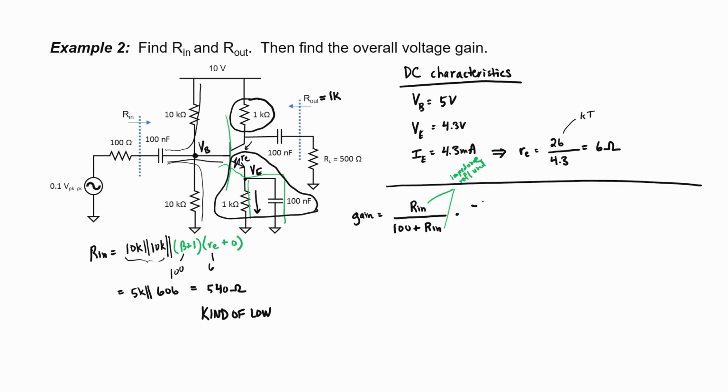So here we have negative 1 kilo ohm. That's the collector side. And then at the emitter side, we have only the R sub E because we have a short circuit here in parallel with 1 kilo ohm. I did not use impedance reflection to bring in the resistors from the base. The reason I didn't use it here is because I used it over here at the input side, and you only want to use it once when you're dealing with the common collector or the common emitter configurations. Let's write 0 in there just to make it clear.